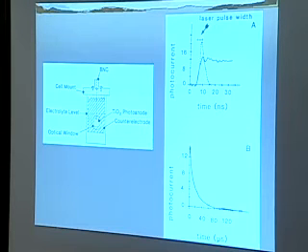So you see over here that we do our laser flash. That's this pulse here, and again, you can see that's on the nanoseconds, tens of nanoseconds time scale. And then we see the photocurrent. You notice that photocurrent is on a much larger time scale, so we have to go to a microsecond time scale here to see the decay of the photocurrent. Again, that's because of the RC time constant of this whole system, which is relatively large.